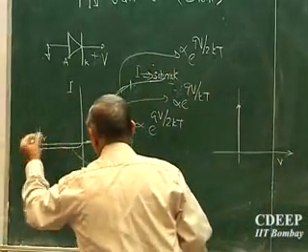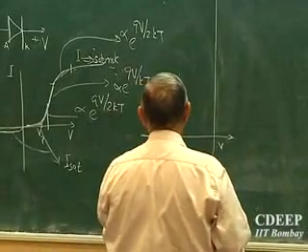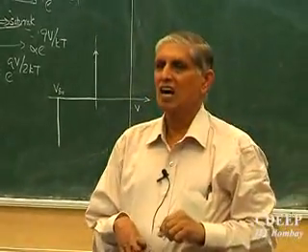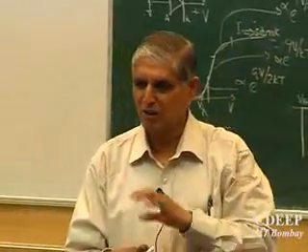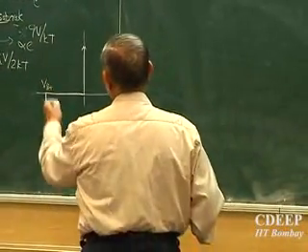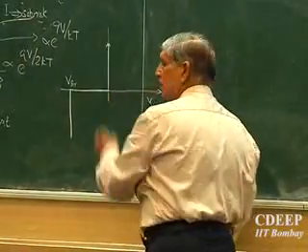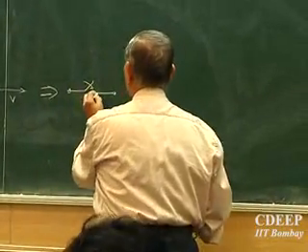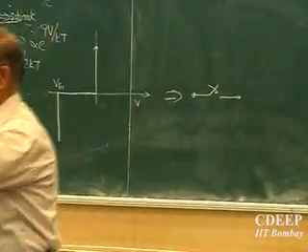So if I assume something here very small, ideally it goes like this, and it's the ideal diode characteristic, which never occurs. The real characteristic is shown there. Ideally it looks something like this. So essentially till this value is reached, this is equivalent to saying it is like a switch, on, off. So a diode acts like a switch. In the ideal state, slightly positive, infinite current, short circuit. Slightly negative, and any amount rather for larger value, no currents.